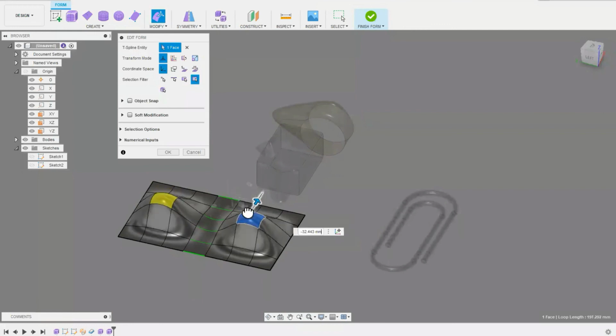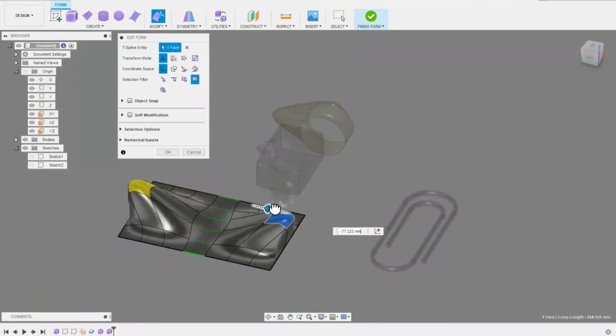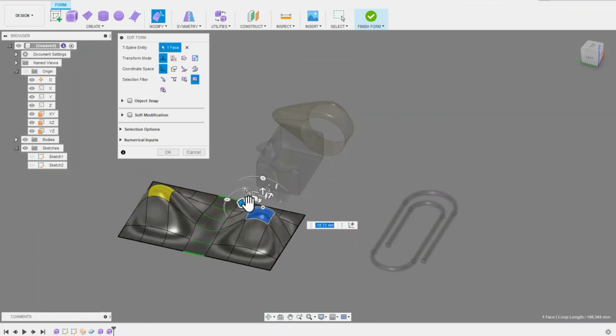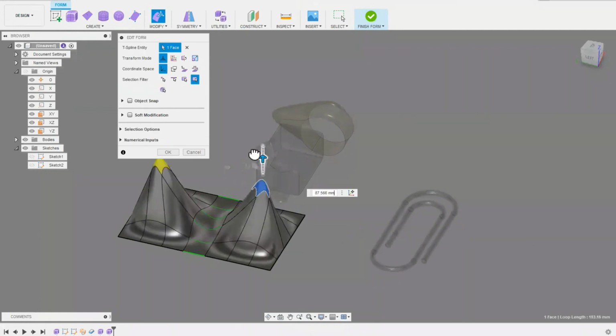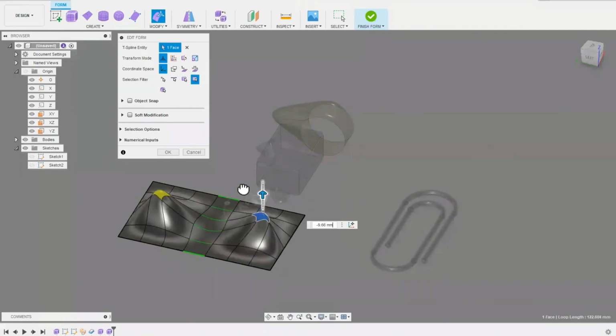And look, let's face it, frequently in engineering, we are doing a lot of symmetrical things. So again, we can simply push and pull now to have that symmetry applied to two separate parts of our environment, if you like. So we can go in and change one of these faces and end up with a symmetry. So anything that's symmetrical, if we put a symmetry line down through the center of those faces, we get the behavior operating like this.